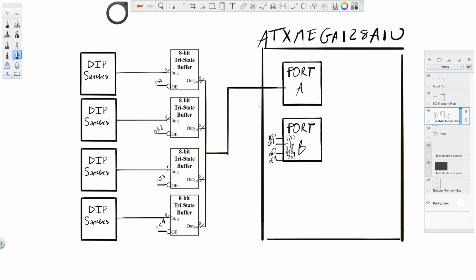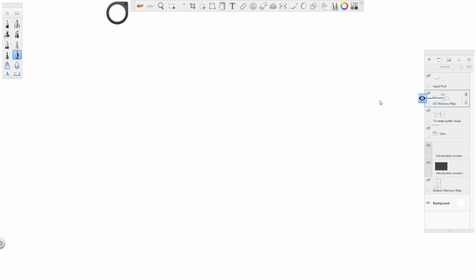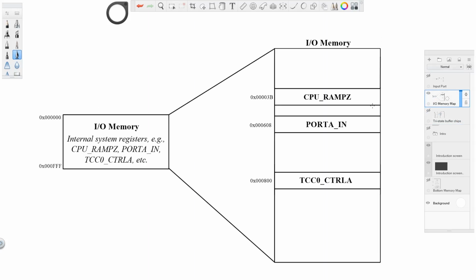So the solution that we're going to employ in this video takes advantage of a native mechanism to the microcontroller that will create a more fluid and dynamic solution than the methods from the first video. This solution is ultimately based on a technique known as memory mapping, in which different peripherals such as memories, LCDs, I/O registers, external devices, etc. are accessible via unique addresses or ranges of addresses.